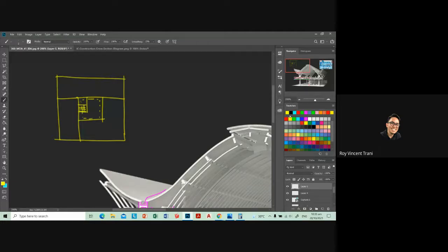And you say you want to put a vent stack on top of this. The vent stack won't work because there is no natural ventilation going in. It's being blocked by these rooms. So the way to make your vent stack work is to make sure there's an open hallway to at least two sides of your building. Because you need natural air for the air to move. If there's no air inside your building in the first place, there's nothing for the vent stack to vent. So just making sure that's clear.